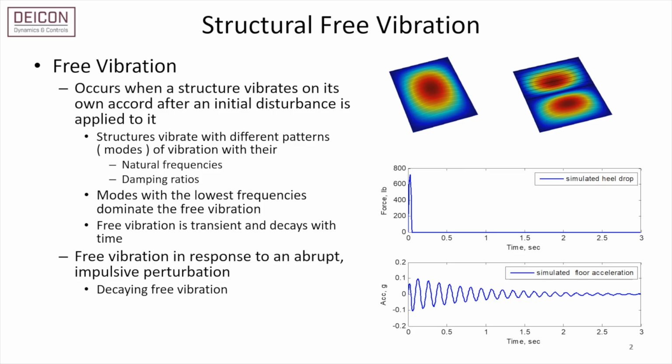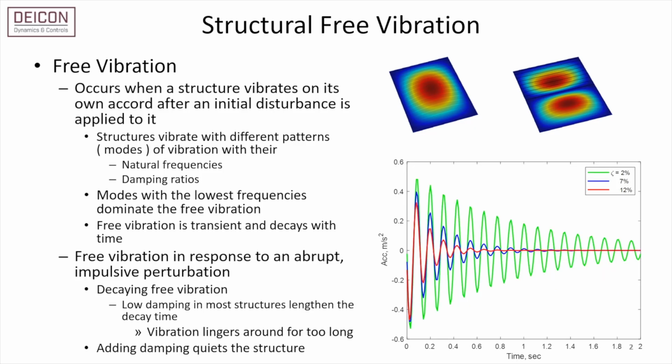Due to the brief duration of such disturbances, the resulting vibration in the structure is classified as free vibration, which is transient and diminishing over time. Many structures lack sufficient damping, meaning they have limited capacity for energy dissipation. This deficiency leads to prolonged decay times for vibrations to cease.